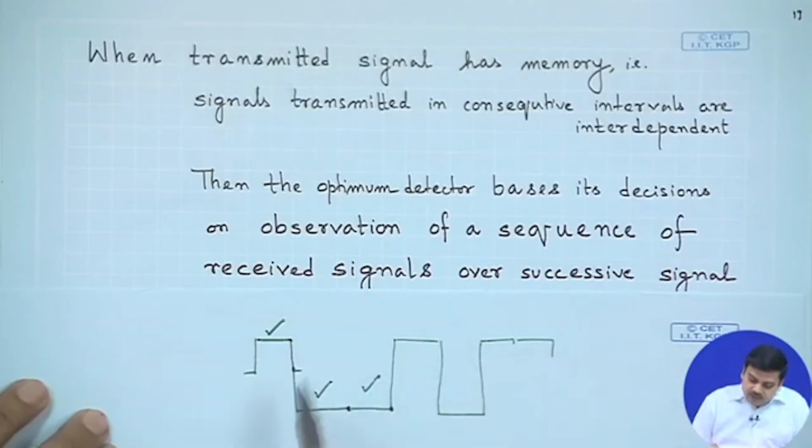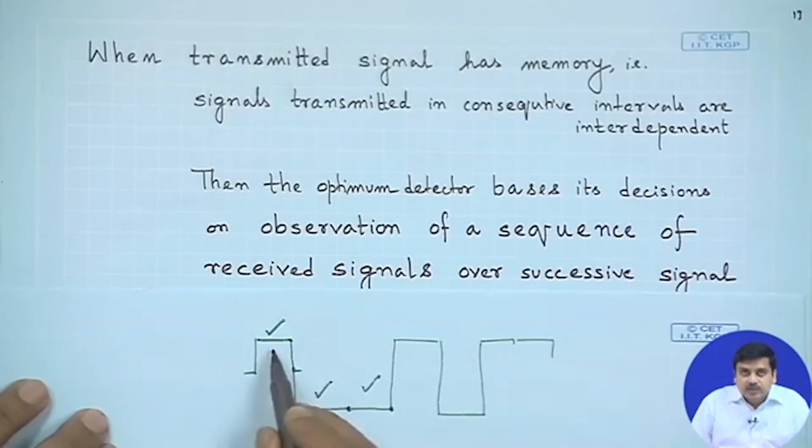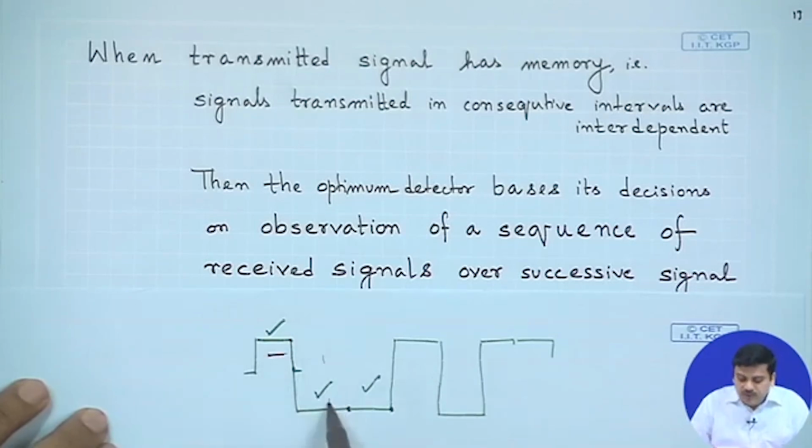But now we say that this signal is dependent on this signal. So, there is some kind of an XOR operation or some other thing. For example, we use NRZI and things like that, where the prior output influences this output. So, the original information sequence is actually spread across more than 2 symbols.